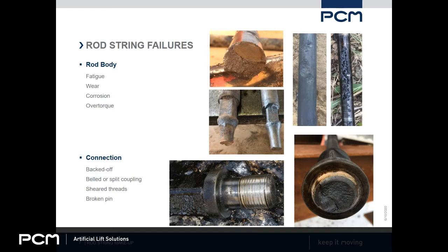Also, if you've set your torque limit on your VFDs or whatever surface equipment you've got to 80% of the manufacturer's torque rating, again, you should never break a rod body unless you've got bad corrosion or wear.